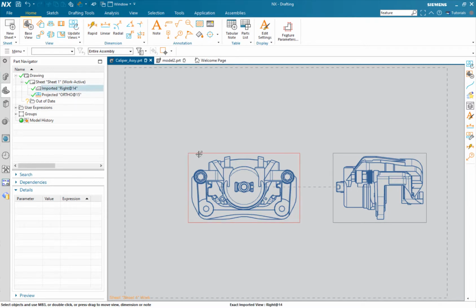We used to tell everyone you right click, you go into expand, and then you start to use curves to draw in your lines. Well, now you don't have to do that. Instead, we can just click on our view and then go into active sketch view.